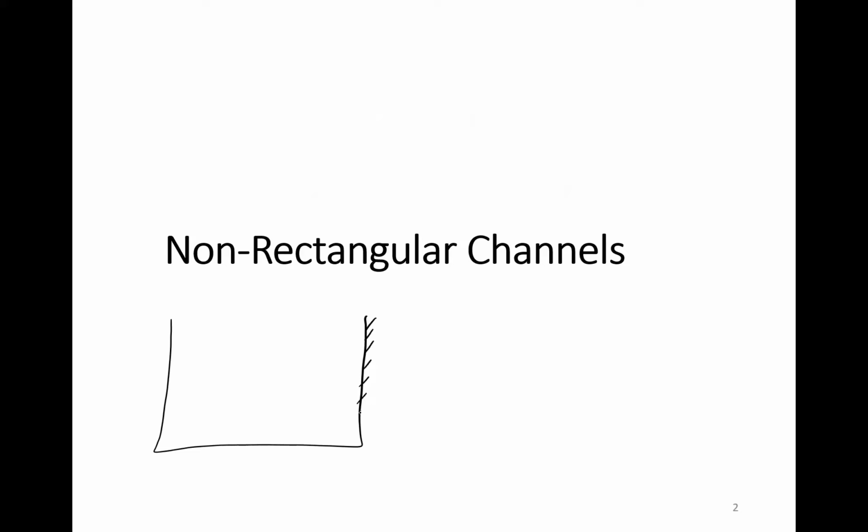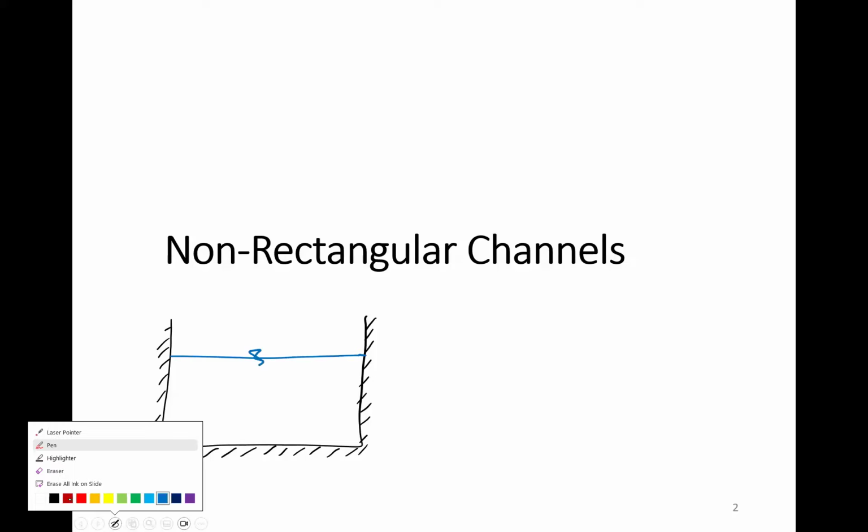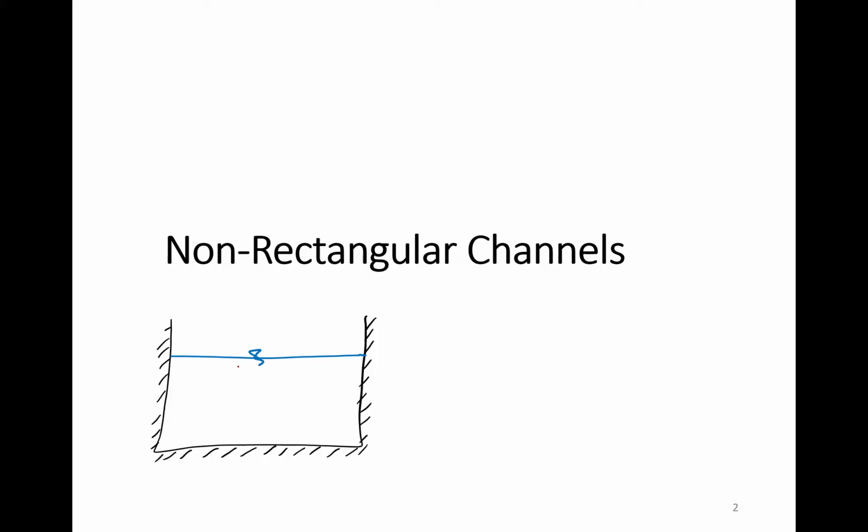Basically, if you cut a section in the open channel and look into the channel, let's say look downstream, because that's the kind of general guide that we follow, it looks rectangular. If the water level is here, the two characteristics of the flow in section are the depth, Y, and the width of the channel, typically capital B.